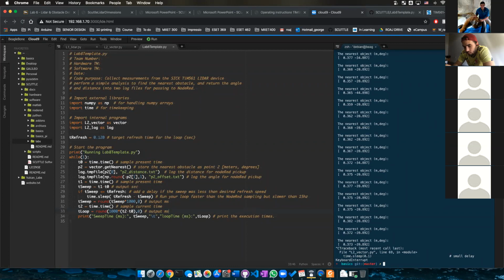So if an object isn't directly in front of it, say off to the side at 50 centimeters, and I'm trying to measure a wall 100 centimeters away, I'm probably going to get either 50 centimeters from my ultrasonic sensor because it's not looking directly in front of it, or a mix of 50 and 100 depending on which pulse it gets back first.